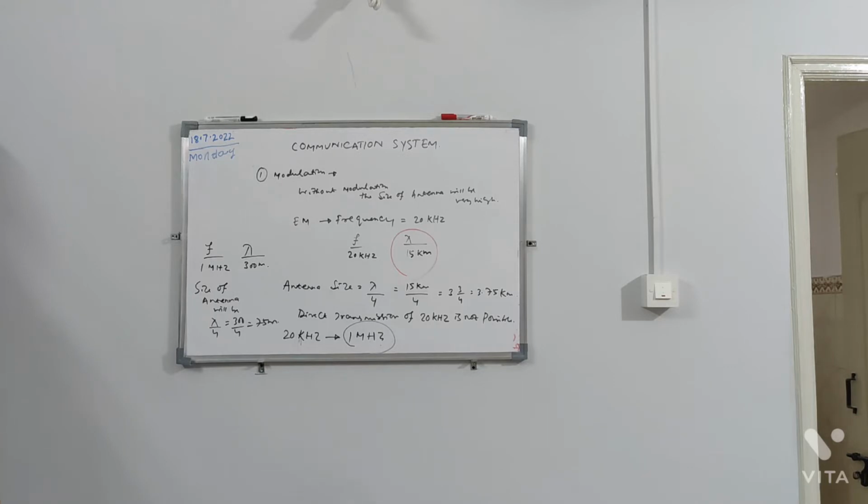And so the need of modulation is that the size of the antenna is equal to wavelength lambda by 4, okay. And another important formula for numericals is that the effective power radiated by the antenna is proportional to (L by lambda) square, okay.